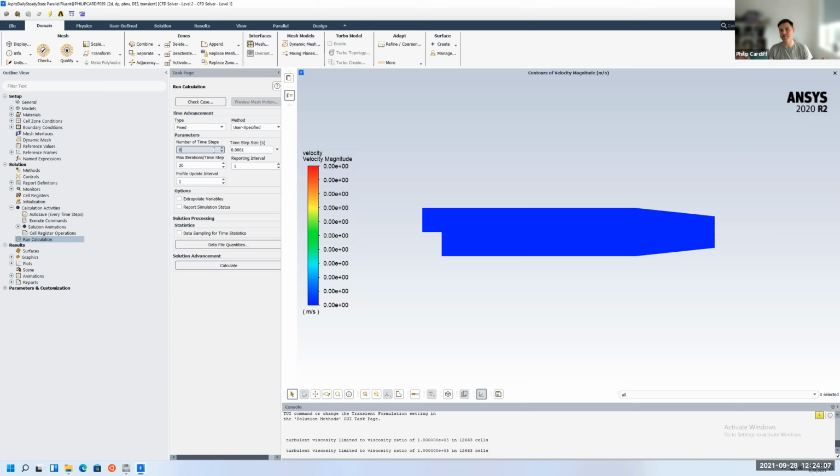By steady state, the flow field is never going to go constant. It's going to be more like quasi-steady state. If you actually ran this experiment long enough, it will always keep shedding vortices, changing around. But the RANS approach we just ran is trying to get the average of all that. So I'm just going to run maybe 100 time steps, and it's going to save 10 pictures.